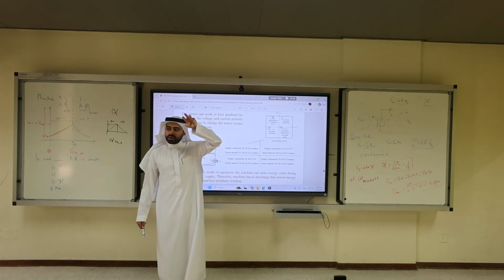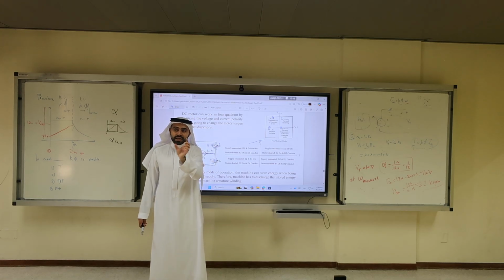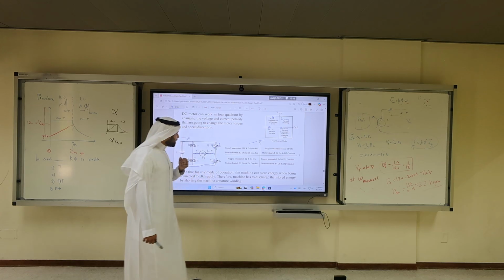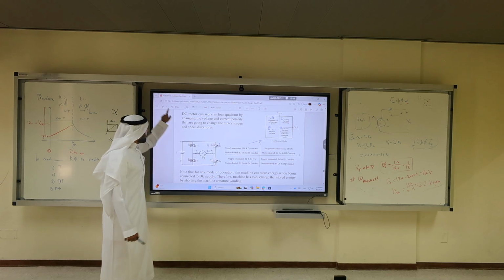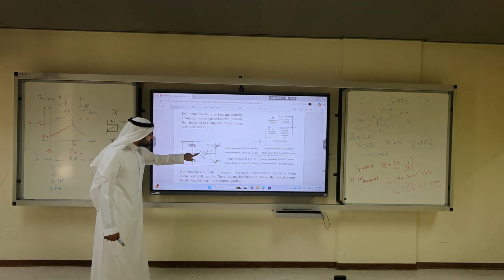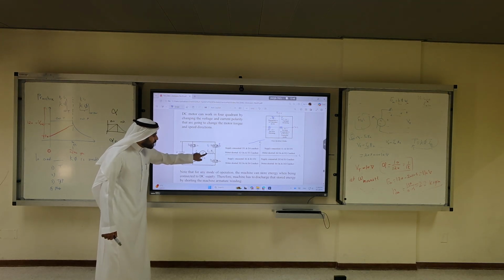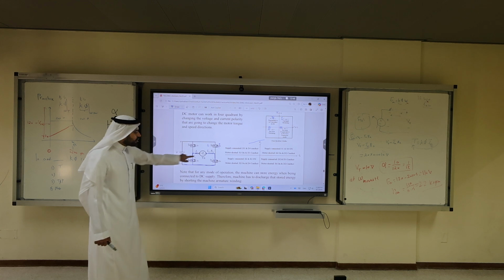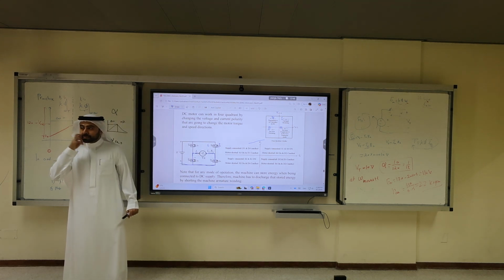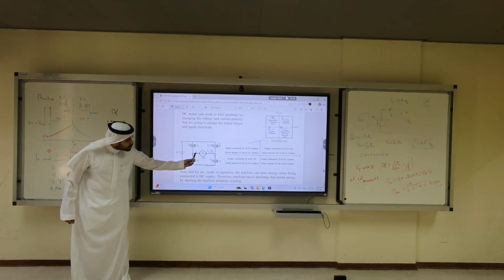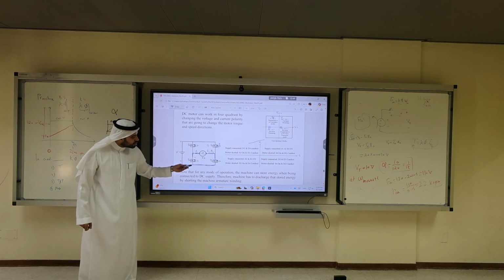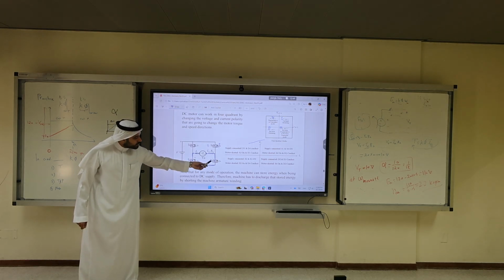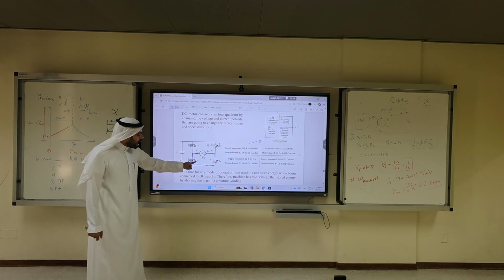But in the motoring mode, I also have some instance where the motor has no power, short circuit. How do I make short circuit? It's very easy. To make short circuit, I have to connect this leg to the negative supply, this leg to the negative supply, and I have my motor short circuited. So to have a motor short circuited, what does it mean? It means both terminals are connected to the negative. So what does this require? S2 on, S4 is on, and the diode D2 is on.